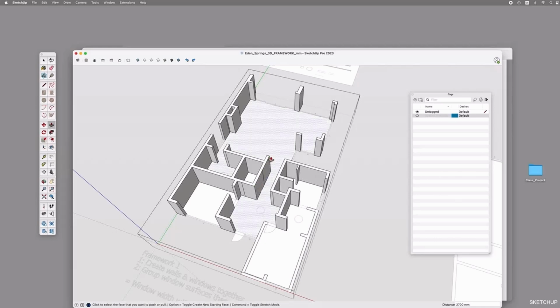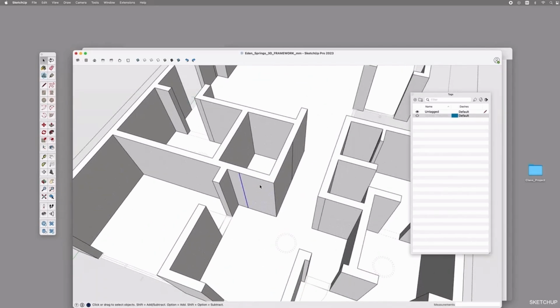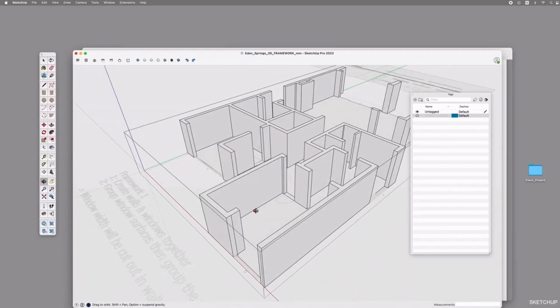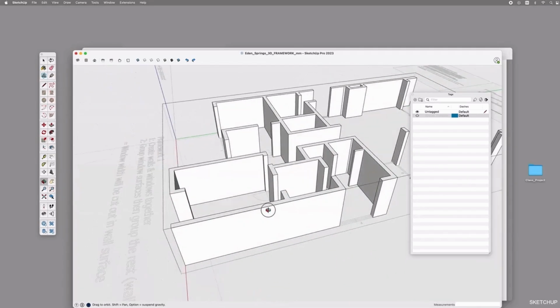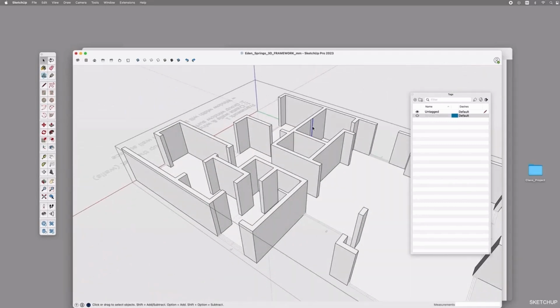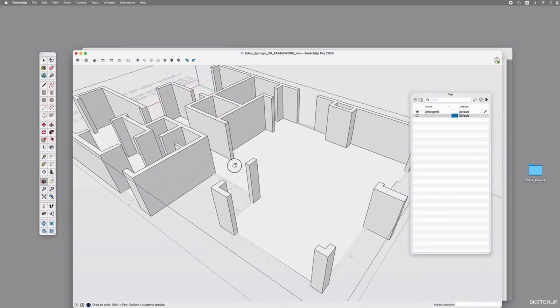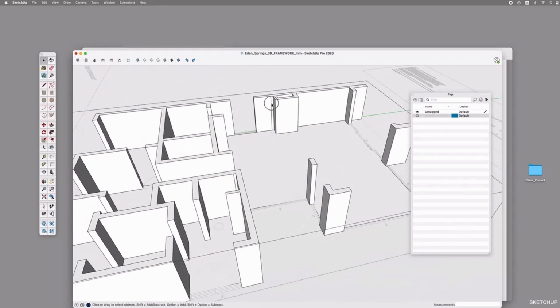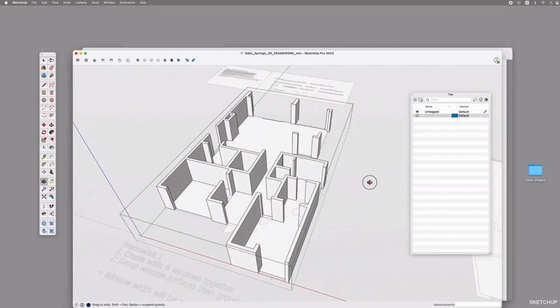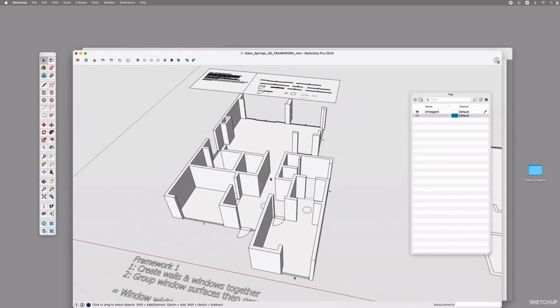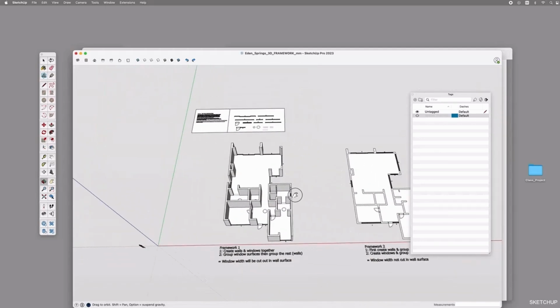Sometimes there might occur some straight lines like this, depending on if you have used lines or rectangle tools when you build this structure. We can just delete the lines to keep it clean. We now have our wall frame. By escape, we can leave the group. Just to see the difference, we will do the same for framework 2.